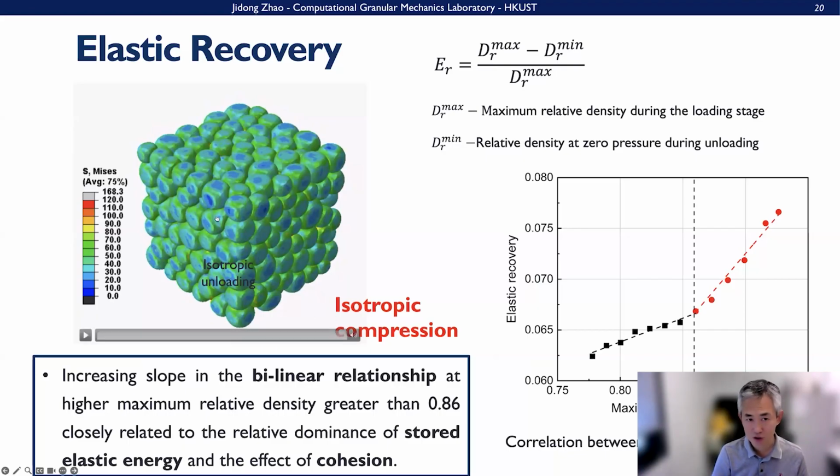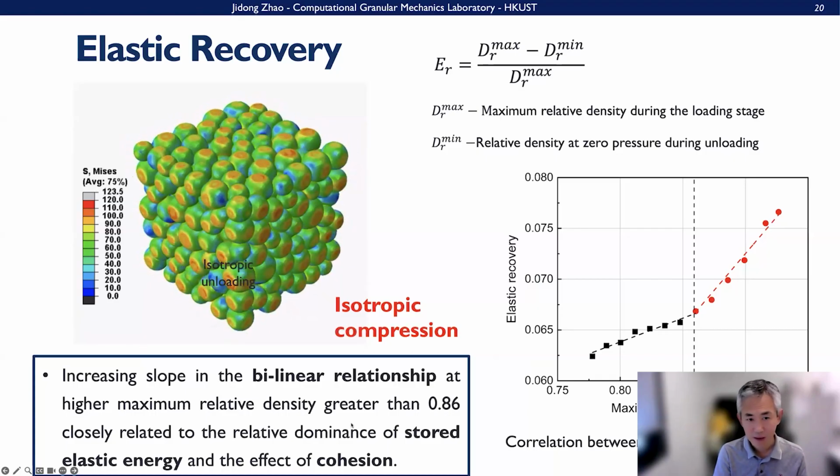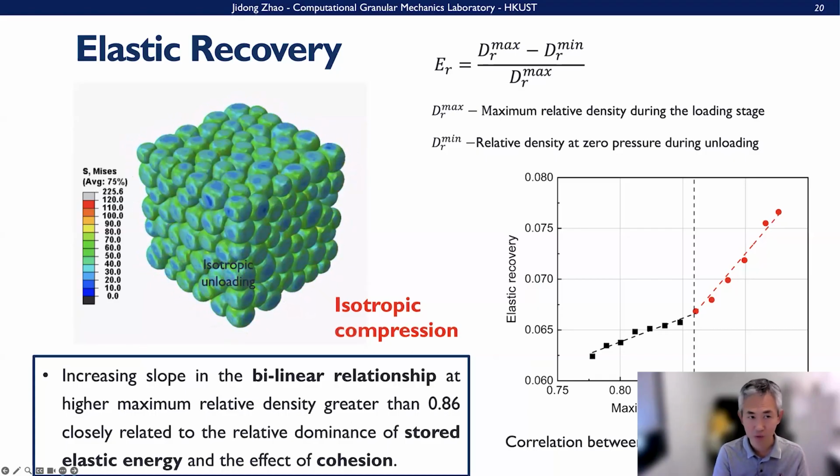And we render the surface of the particles becoming severely flat, okay? And then once we stop the compression, we can remove the pressure, remove the walls. And after removal, you can see there is a certain instant rebounding. We call it elastic recovery here.